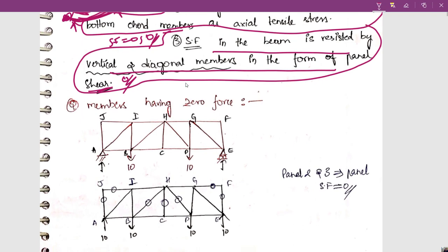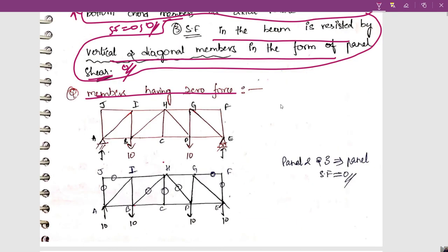So he is asking us to find members having 0 forces. Now let us see if there are any 2 members with no external force. Yeah, I can find 2, right? And here also at this corner, I don't have anything. Now let us see if there are any 2 axial forces and a third force meeting making some angle. So is there availability? Yeah, here I found 1.